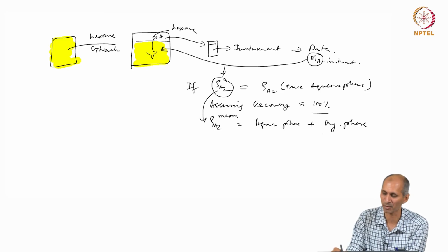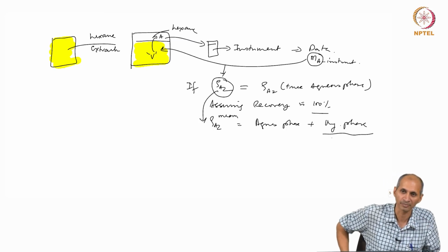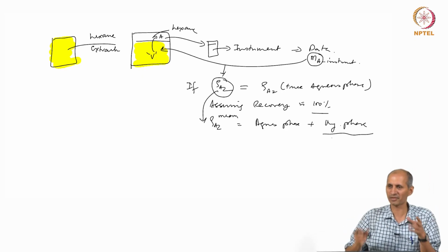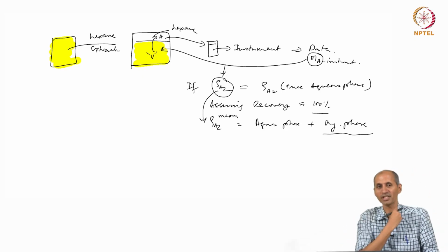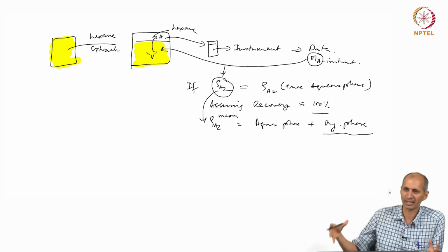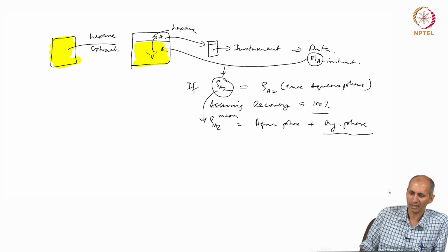A significant amount of organic chemical is sitting on the organic phase, right. The KOC is very large, 10% of the original organic phase is still a large amount. So, it is very likely that you will see a large concentration if you take the entire water sample as it is and extract it, against the concentration you have estimated based on the calculation, true aqueous phase. Okay.